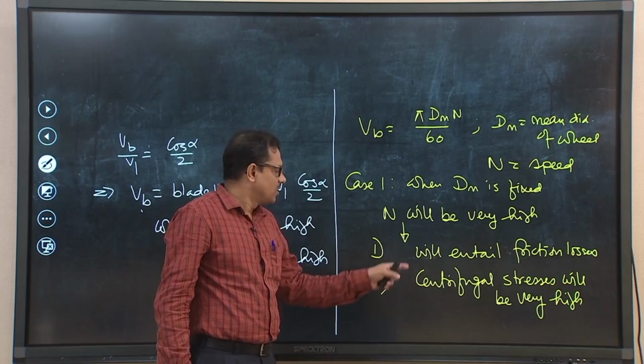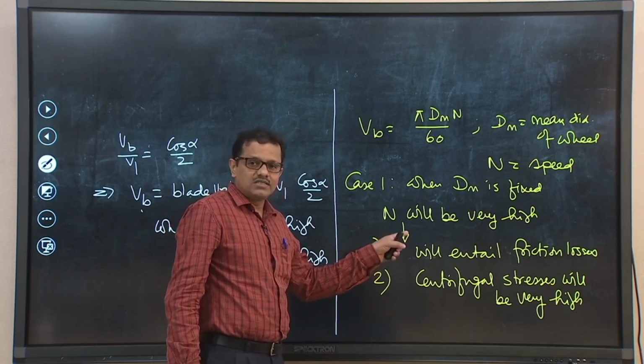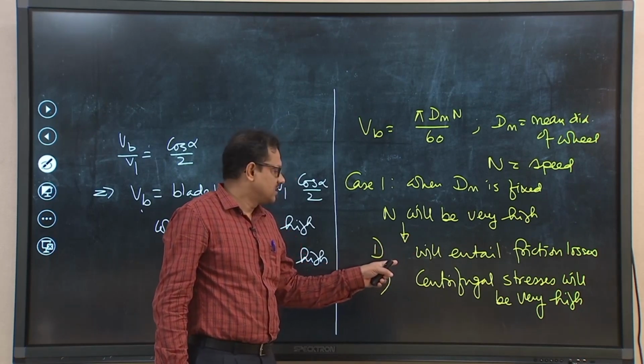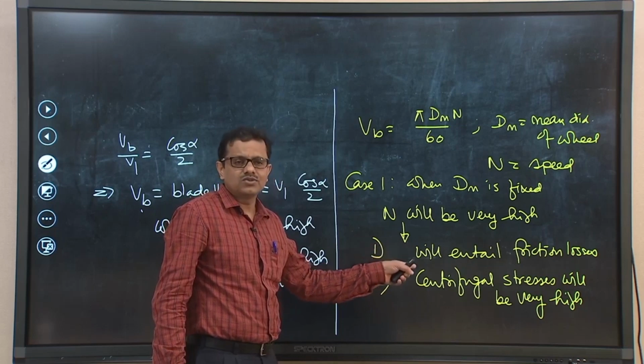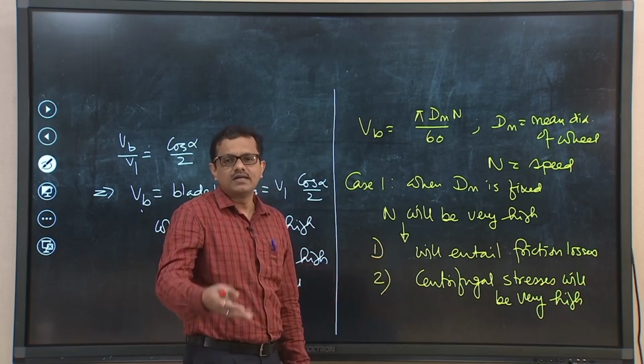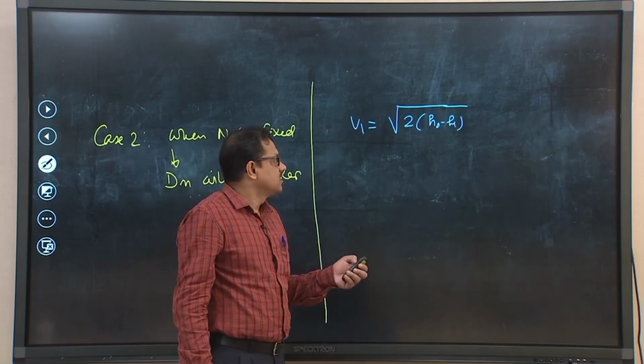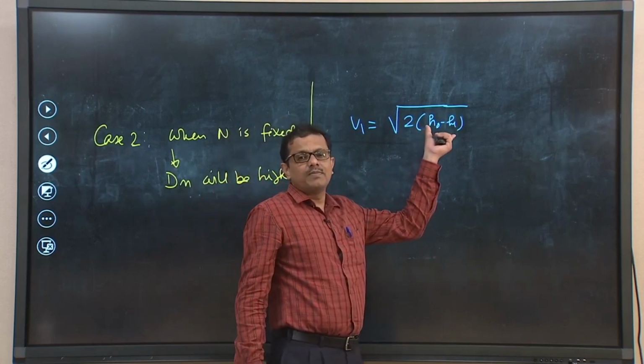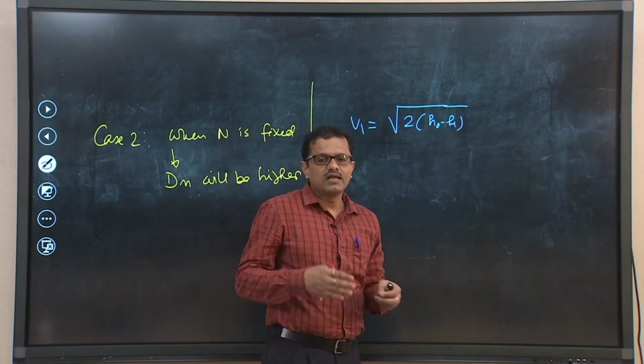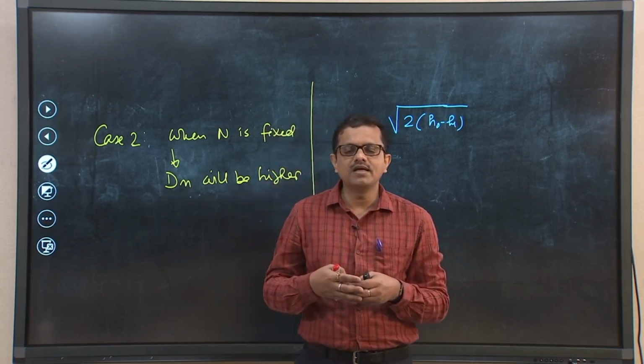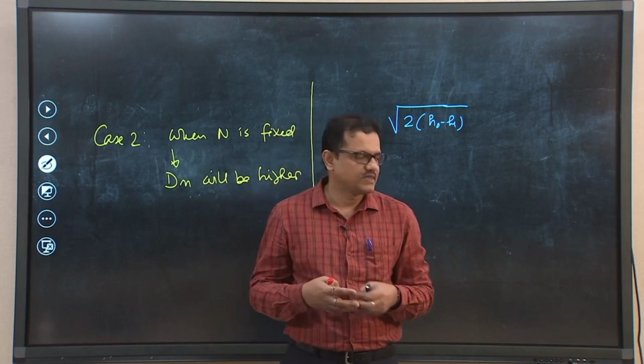So, we need to design the unit in such a way that all these issues will be circumvented, while securing the same total enthalpy drop, and that is what is done by the compounding of steam turbine.